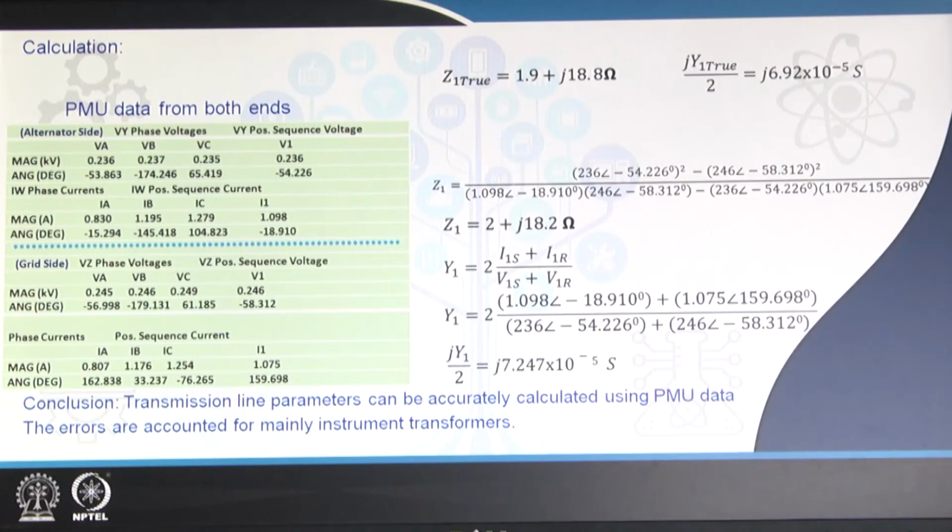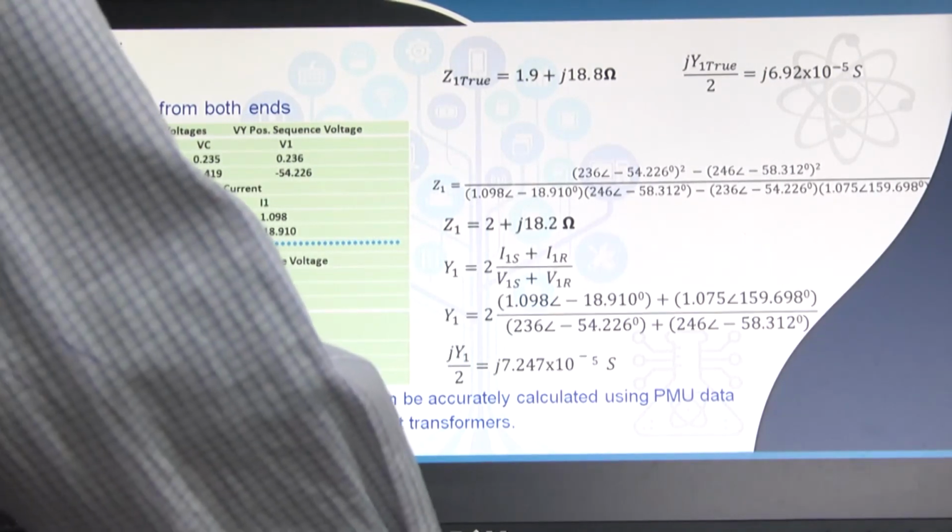So, this gives us scope to apply it in real time also, by obtaining the real time data from the two PMUs on both sides through dedicated communication systems to monitor the parameters. Such parameters are used for relay settings, and also for the thermal capability of the line, which governs how much power can be dispatched in real time at a particular instant.